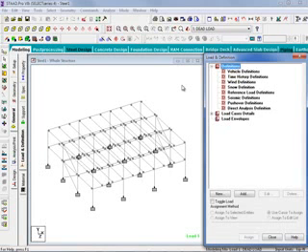Once these load definitions are created, they can then be incorporated into one of our load cases as a load item. For this training, we'll be focusing on our wind definitions, which will be used to define the values for all the parameters required to generate wind loads according to the selected code and design standard. As wind loads are developed for a structure, it is not uncommon to find that the values for these parameters may vary depending upon the particular wind direction being considered.